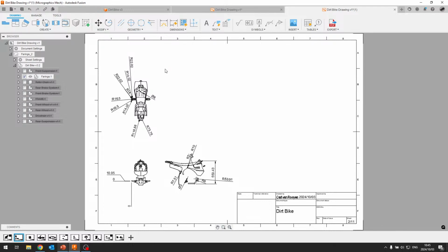Yeah, so Inventor and Fusion do have a link if you work with your Autodesk Drive. So over here we'll see Autodesk Desktop Connector, that essentially allows you to save your Inventor files in a cloud drive, and you would then be able to open them from inside of Fusion.